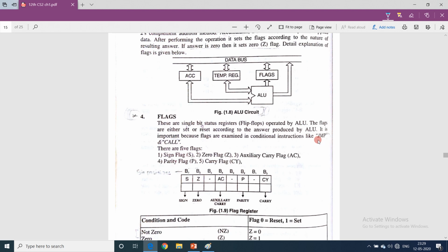These instructions we will learn in chapter 2. So you don't have to worry about where we will come to know which instruction is what. Of course, all the 74 instructions are explained in detail in chapter 2. So jump is actually written wrong here. Jump is an unconditional instruction, not a conditional instruction. But call is conditional. We will learn about this in detail later. I hope you are clear with conditional instructions.